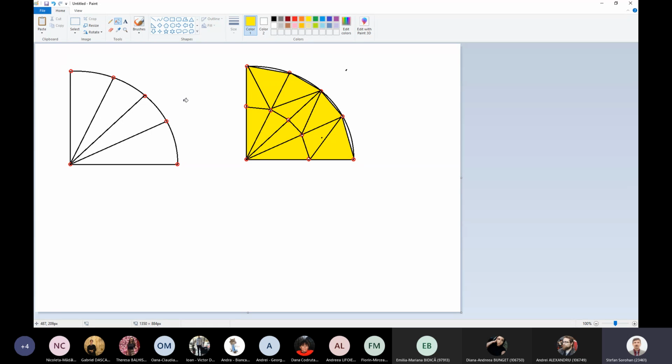So this is the reason that this mesh is better than this one, because here I have only 4 elements. Here I have 1, 2, 3, 4, 5, 6, 7, 8, 9, 10, 11, 12. So a lot of work. And if you check that, the results for this one will be exactly the same as you will obtain using this one. No more difference. Okay.